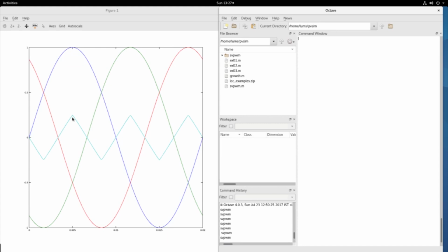See, the third harmonic will not contribute to a rotating space vector, because you have the minus 2 pi by 3 and minus 4 pi by 3. Three times that becomes 2 pi, and therefore there is no phase difference and no contribution to a rotating space vector.